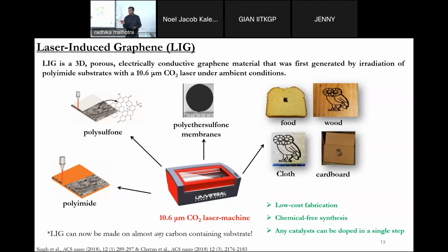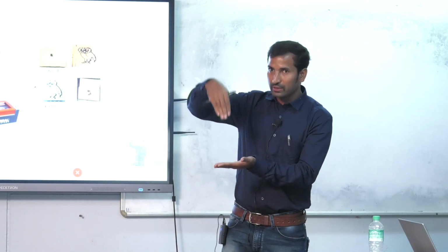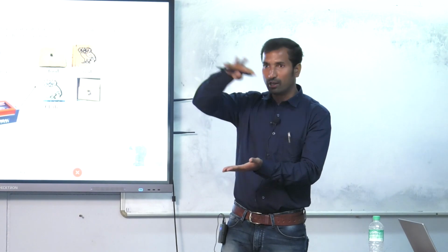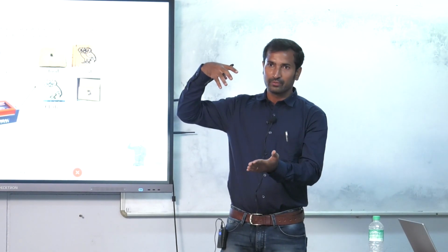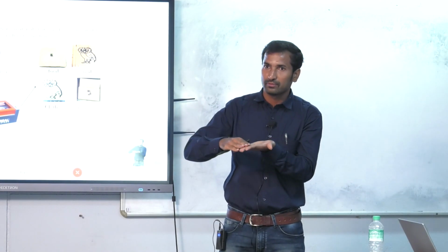Like if you do a small scale test in a petri dish, if you keep a small coupon of your membrane and put only a few bacteria, then you will see the antibacterial properties. It can kill or it can create that inhibition zone, that small zone. But if you go to the real filtration process, there is a permeate drag force. We are applying pressure, so all the bacteria move towards the membrane surface.